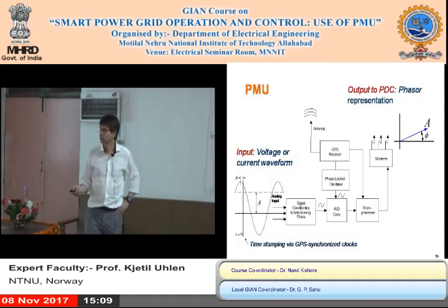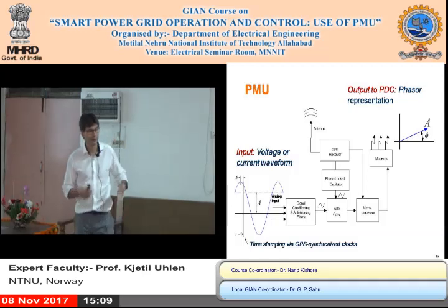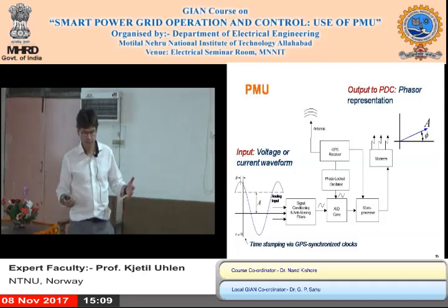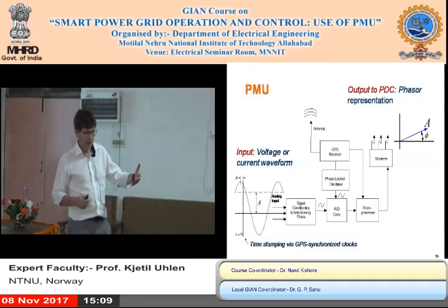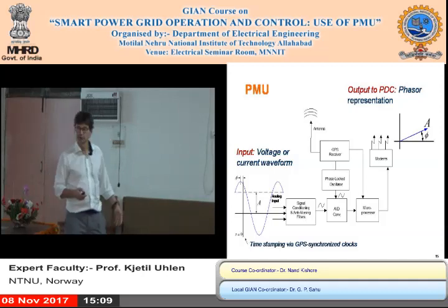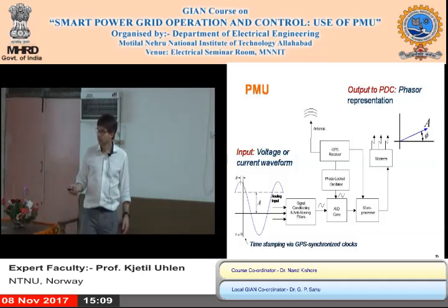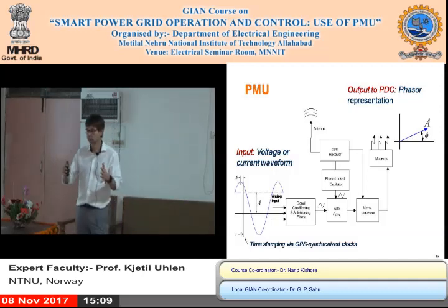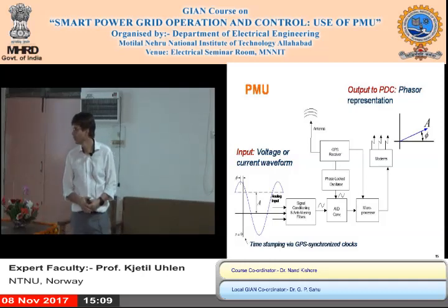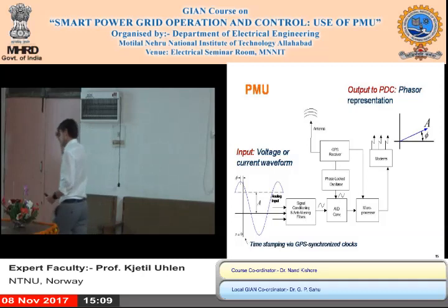And then you would normally send the measurements to what we'll call a phasor data concentrator, which is another computer, perhaps connected to a database or a storage, so that you align the phasors from all the PMUs in a synchronous way.